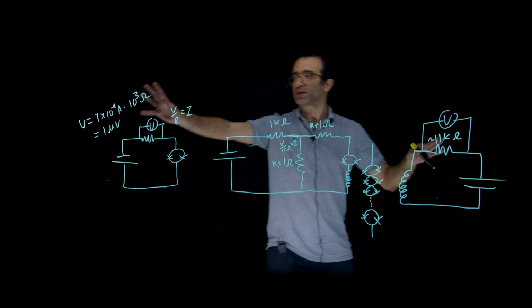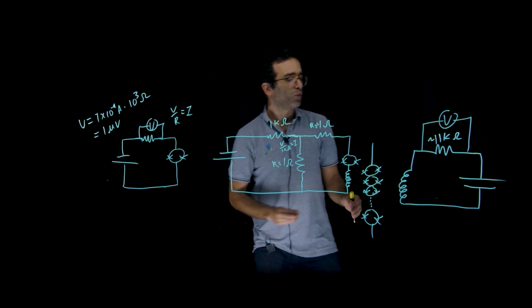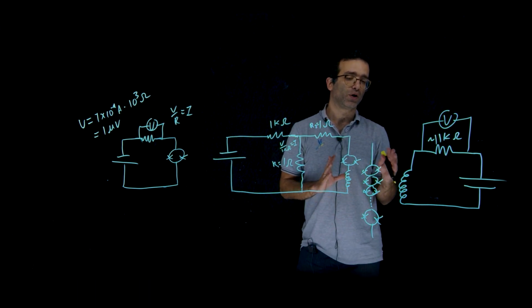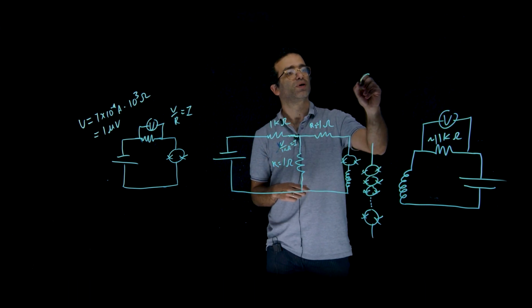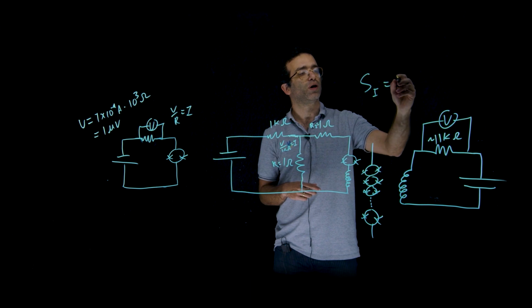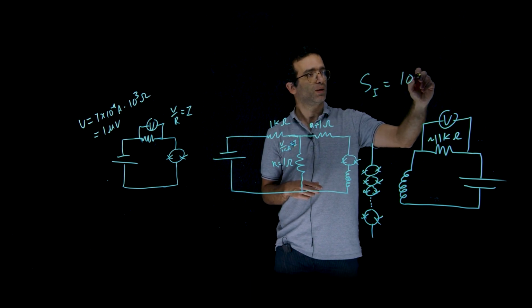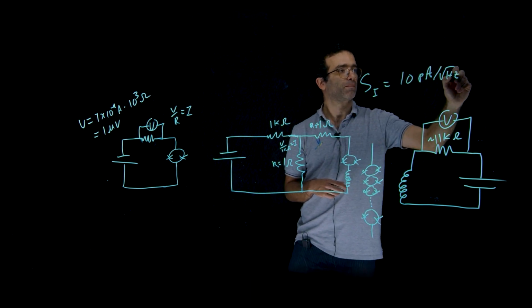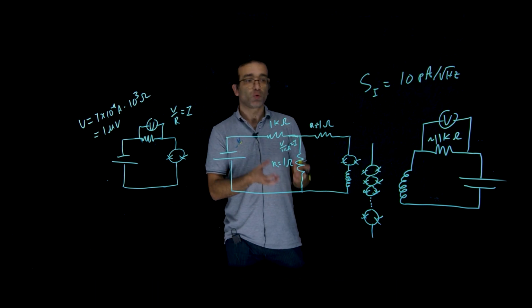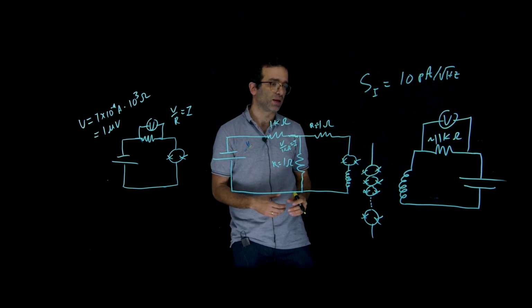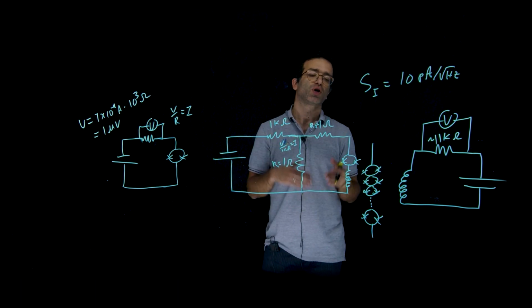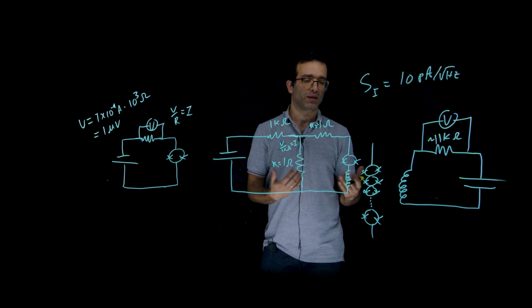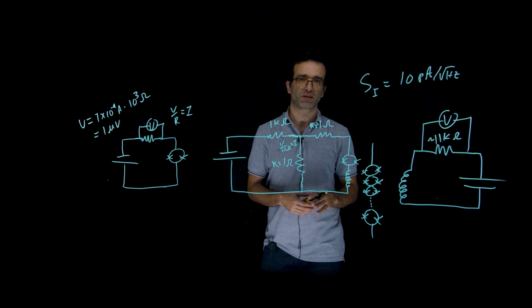And when you put all this with the gains together, we end up having a noise sensitivity here of the order of 10 picoamps per square root hertz, which is enough to do our SQUID readout. And in our specific case, this is the SQUID on tip. This allows us to get a single electron spin sensitivity and even better.